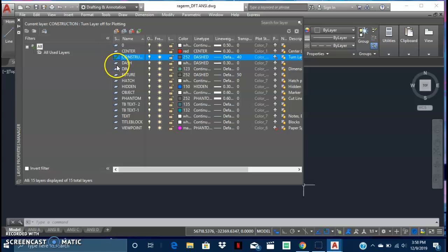And then there's dash lines, dimension lines. You'll use those at the end of the drawing phase when you're dimensioning your whole project. And then future lines, again, just another helpful line type for when you're previewing what you're going to make in the future. Hatch, that's when you're filling in certain objects to help emphasize the cutoff of a certain object.